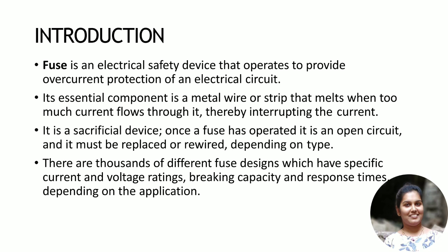So fuse is nothing but an electrical safety device that operates to provide overcurrent protection of an electrical circuit. The essential component in any fuse is a simple metal wire or a strip of wire that melts when too much current flows through it, thereby interrupting the current flowing into the load circuit.